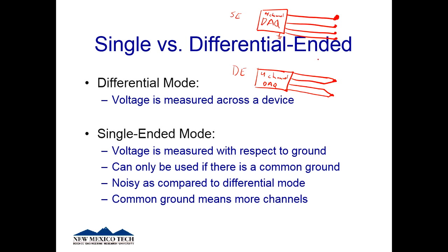And the idea with this is, we'll talk about antennas next week as well, but the longer the wire I have, the better of an antenna it acts as. If you're building an antenna, that's great, but the reality is, if I'm trying to measure pressure over here, I don't want this piece of wire absorbing a bunch of other signals, because that's just adding to my noise.